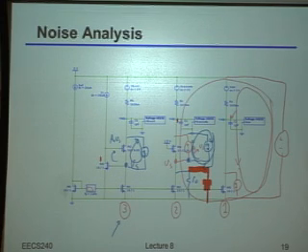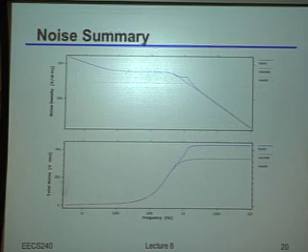So it is true that this will probably have slightly more noise than number 2, but all 3 of these should be very comparable from a noise performance standpoint. In particular, as long as you make sure the capacitance on that source node, this Vx that we typically call it, is sufficiently small. That's really the only dominant effect that causes a lot of extra noise current flowing through the output. So just to be sure, oh, yes?